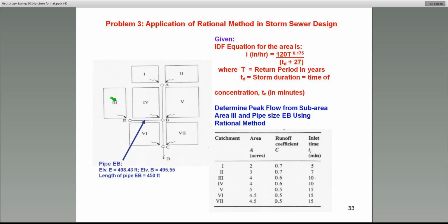You're going to pick the maximum travel time along all the possible paths of runoff to that point B. In this case, it will be from this manhole, through this pipe to that manhole, or directly from area 4 or 5 draining to that point, shown by these squiggly arrows, or from area 3, but area 3 comes through the pipe, so you'll have to include the travel time in the pipe too. So you compare all those travel times and then take the max for the time of concentration parameter at the inlet manhole, point B.